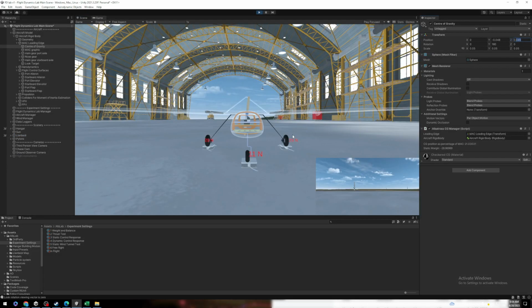Now we will load the weight and balance data for our aircraft. The aircraft is displayed resting on three weighing scales, each indicating the mass reaction on that particular scale. By knowing the distance between the wheel relative to the aircraft and the forces acting on them, we can compute the moment on each wheel, which allows us to get the CG's location. Also, adjusting the Z value of the CG, we can observe the changes on the locations of the CG and the reactions on each force balance.